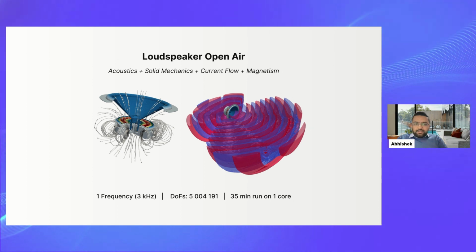Yeah, so these are the results of the loudspeaker driver in open air, including all the physics: acoustics, solid mechanics, current flow, and magnetism. On the left, you can see the magnetic flux lines, and on the right, you see the isosurfaces of pressure, low and high values. This simulation was run for 3 kilohertz in 35 minutes on one core.